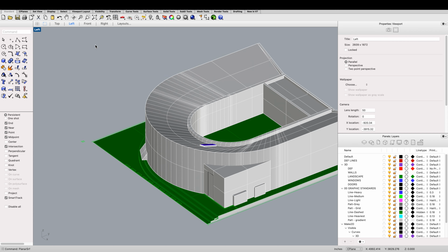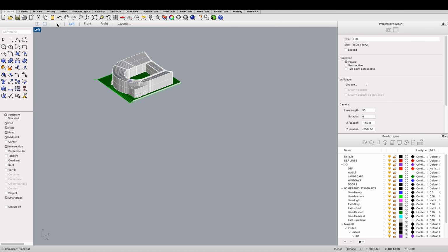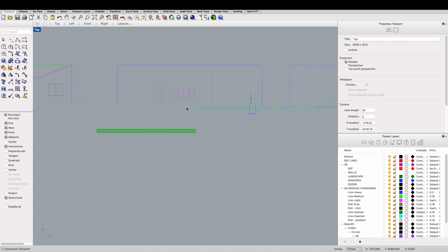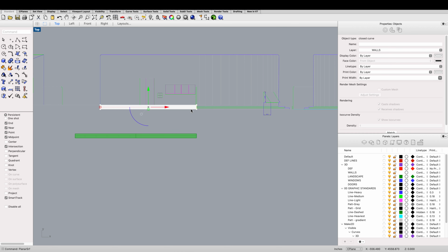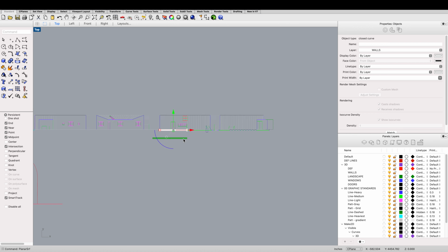The other thing you could do, if your images are super tight, is just draw like this, make a planar surface, and then just stick it on the side of the house. Is that what that green box is? That's what the green box is. It was from the other one. But again, we're not going to see that side. So don't spend too much time doing something you don't see.